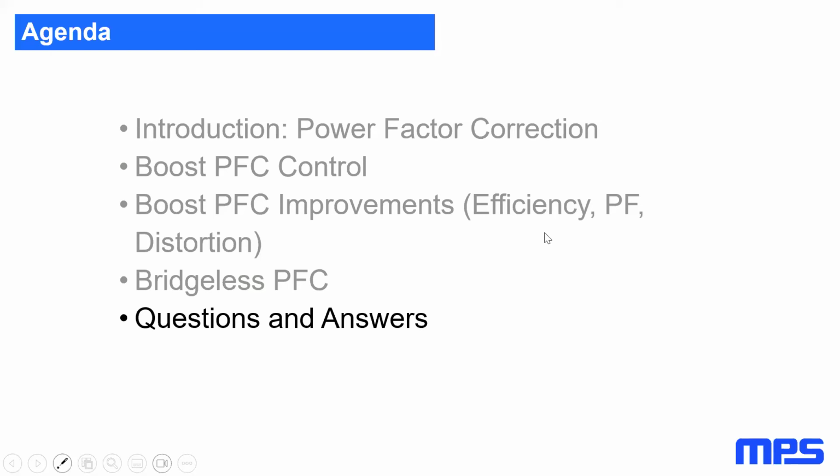In that case, a CRM solution, even though it might have higher harmonics and higher EMI, might still be cheaper, even if you have to have maybe a bigger filter in front, or you have a little less PF or a little higher distortion. But if it's good enough and you achieve your target at a good price and the size is acceptable, then you will use the cheapest one.